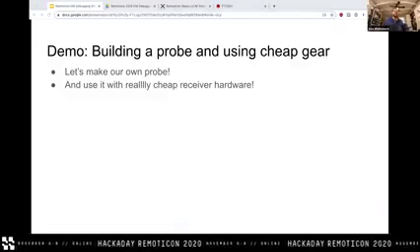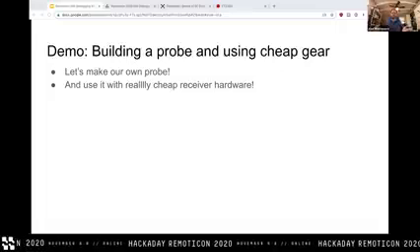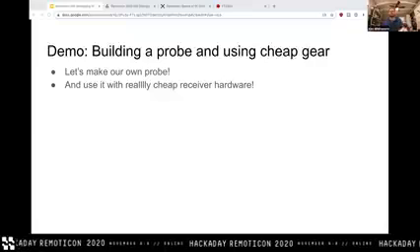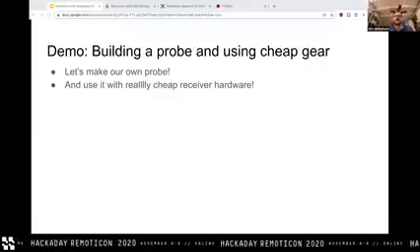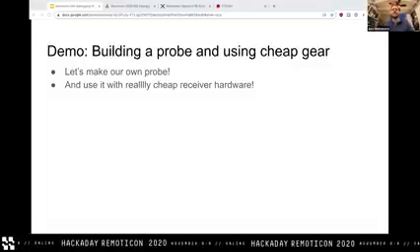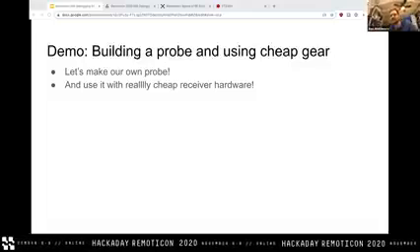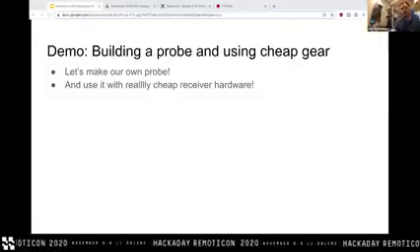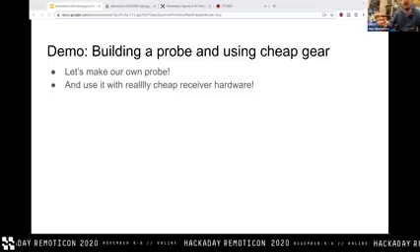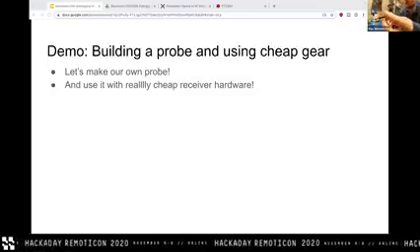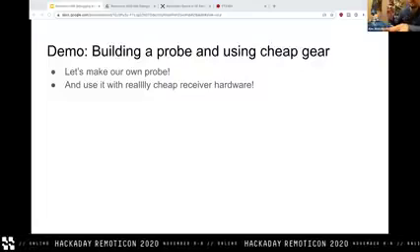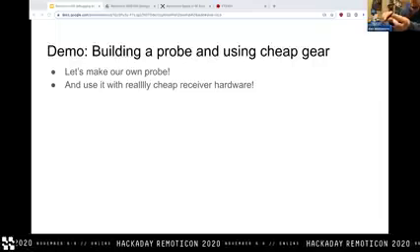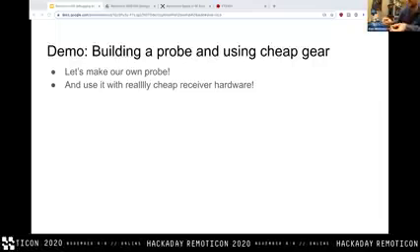So at this point, I want to actually quickly build a probe and show you that process. So this will be a little bit of a catch up before I dive in with the SDR side of things and show you how that compares versus the expensive RSA gear. So I showed you before this probe, which is basically my favorite of all of them. This probe is literally the same as this guy. It's just a loop of wire tucked up neatly and tightly into the tiny little tip of that plastic housing.